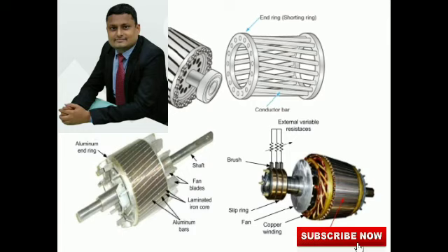What are the disadvantages? As we all know, everything has some advantage and some disadvantage. So the disadvantage of large air gap is the magnetizing current will get increased, and the power factor will also get reduced. So once again, advantage of large air gap: increased overload capacity, increased cooling, reduced magnetic pull, reduced tooth pulsation, reduced noise. Disadvantage: increased magnetizing current, power factor will get reduced.